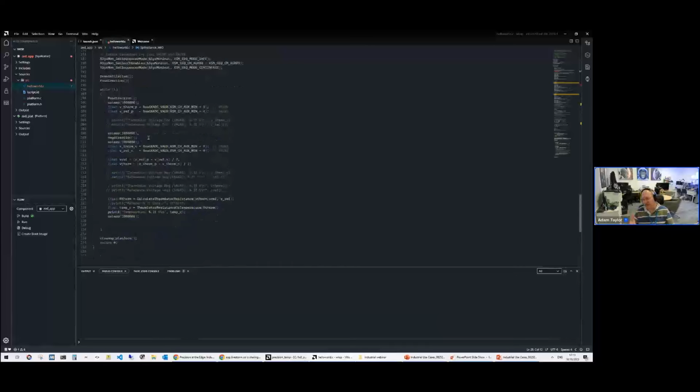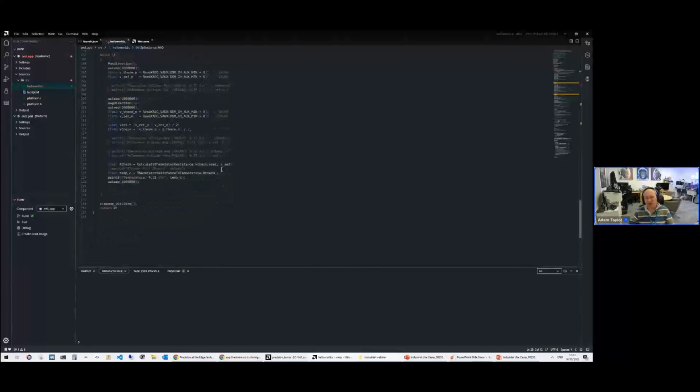We're going to set the negative direction. We're going to wait for the voltages to stabilize again, and then again we're going to read those voltages and store them in these variables, and then we're going to calculate what those voltages actually are for the reference and for the thermistor. Again, a little bit more debugging code if you want, but that's not included and not necessary in this.